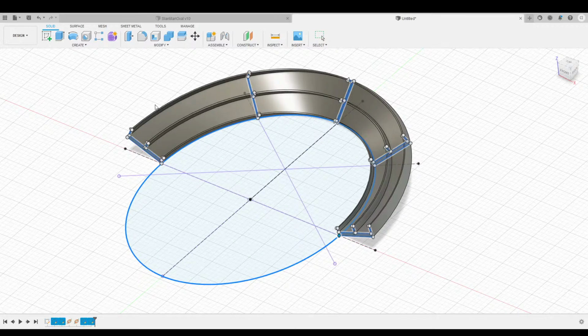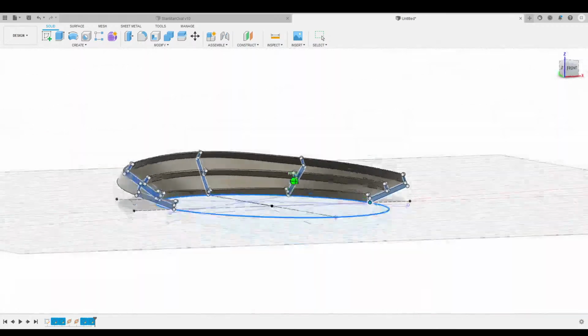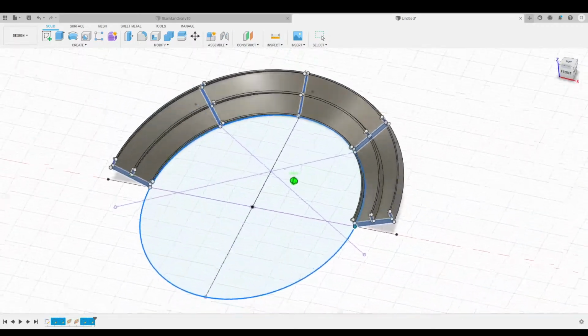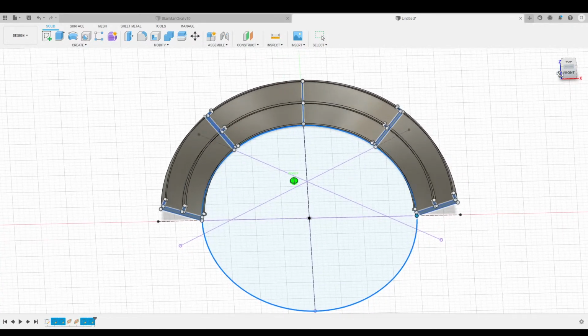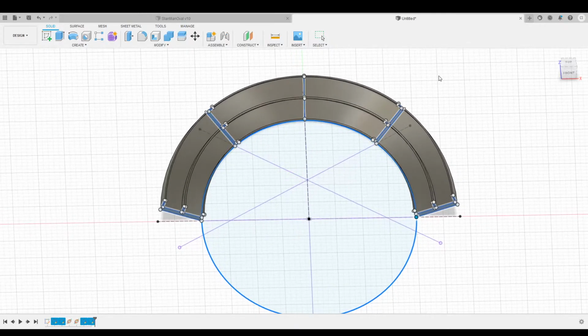But stuff starts to get a little weird when you do that, because the splines might not necessarily have the same strength on each of the points that you're placing. But that is a way to basically force Fusion to say, look, this is a rail. You need to connect this dot to this dot to this dot. I've found that if you can get it to do the center line, it's just a little safer. A lot of the older curves that I've done have used the rails and splines, and things can become a bit of a mess.